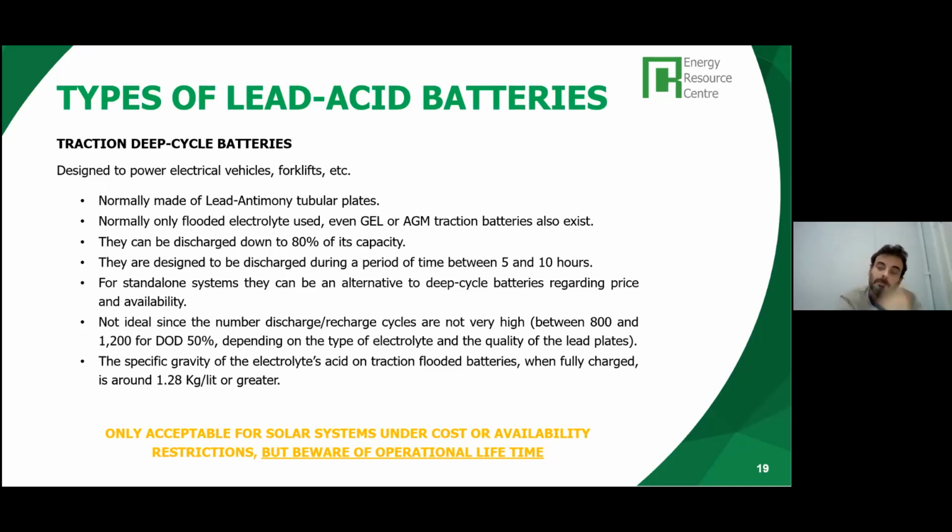So this makes them a bit more convenient for solar applications, even though they are not ideal, because the number of discharge and recharge cycles is not very high. They will not last very long, but they are cheaper than what we call the solar batteries, so they could be an option if there are restrictions in the project, such as cost restrictions or availability from suppliers.